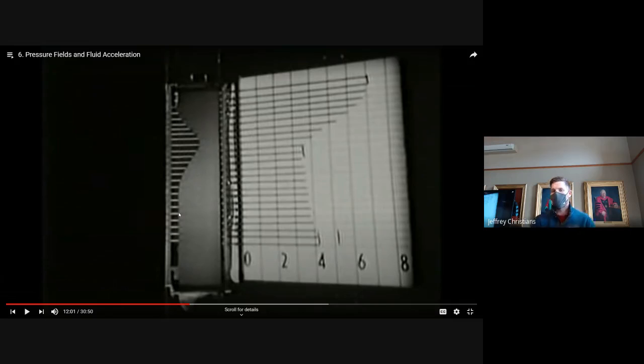So why do you end up with a huge loss in pressure? Because you're turning that mechanical energy, which was pressure, into heat because of all the mixing that's happening in the wake of this bump. So you're not losing energy, because we can't lose energy. Energy is conserved, but you're losing mechanical energy because of all the mixing that's happening in that wake.